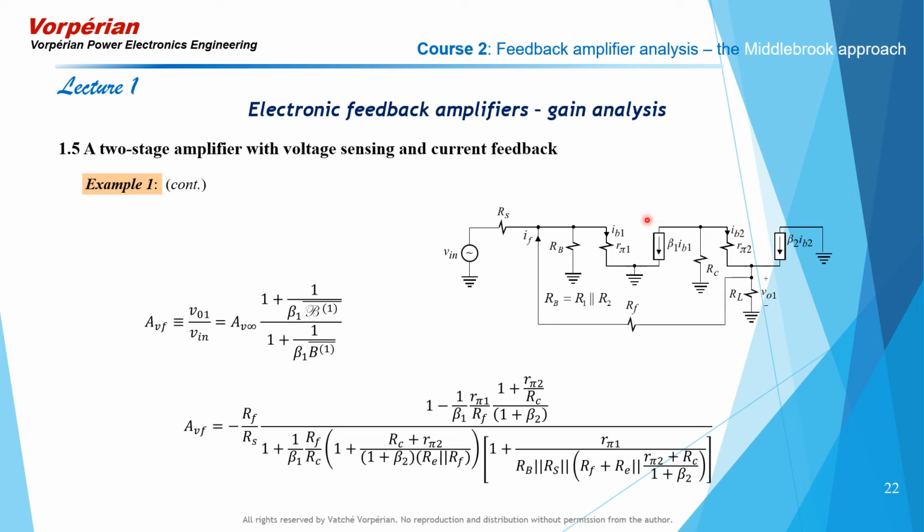And it's an inverting gain. When we kill the gain of the amplifier, make beta 1 all the way go down to 0, then the inverting path dies out, and the only path left for the input signal to reach the output is through the feedback connection, which is a non-inverting path. And the gain through that path is nothing more than an attenuation given by the voltage division that you get from the resistive connections that you have.